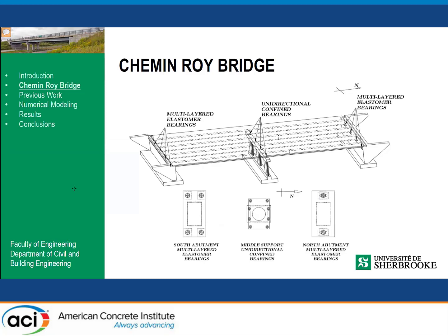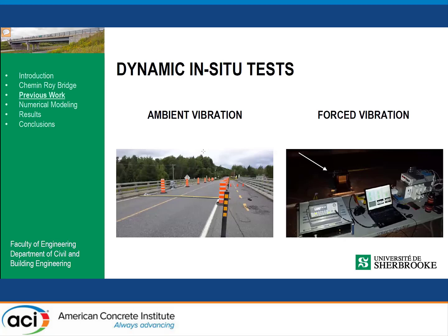The multi-layered elastomeric bearings of the south abutment here, and the unidirectional confined bearings here on the bridge bent, are fixed in both longitudinal and transverse directions. The movements are restrained in the transverse direction, but allowed in the longitudinal direction for the north abutment. The information we collected during the in-situ dynamic tests allowed for the calibration of the 3D numerical model for the bridge.